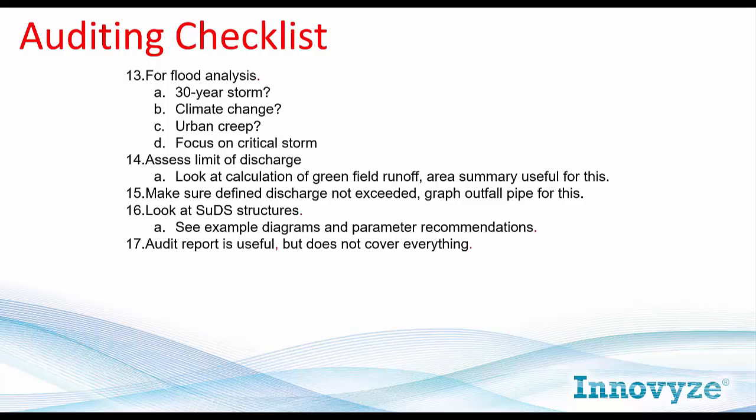Has climate change been allowed for? It's not always required, but if you specified that it is, it's your choice, and then it's your job to make sure that it has been included. Similarly, urban creep. Remember, there's a specific place now in InfoDrainage for urban creep. So at this stage, we think we've designed all the pipes so that they don't flood, don't surcharge. They've passed the 2 tests.